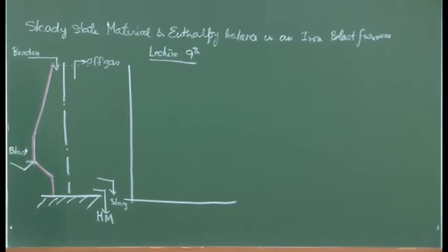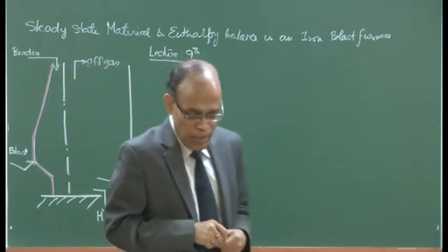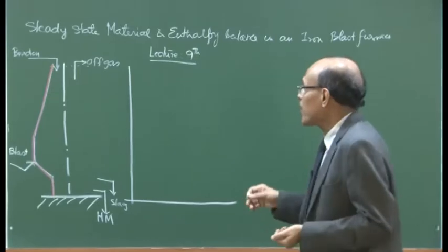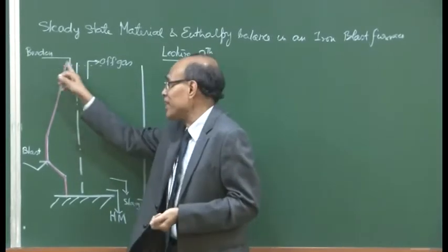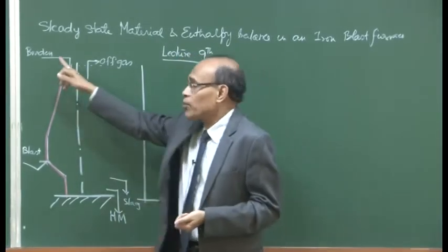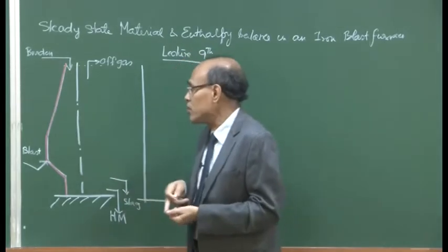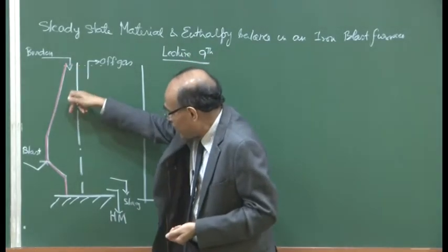Now, to recapitulate very briefly, we charge solid burden material from the top of the furnace, which comprises iron bearing material as well as coke, and that solid material gradually descends.